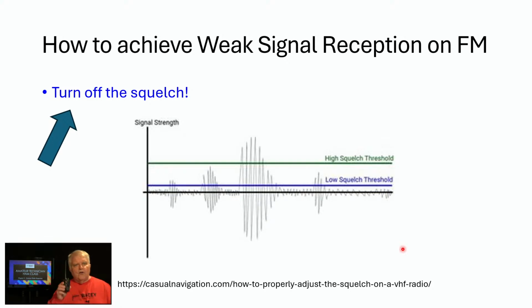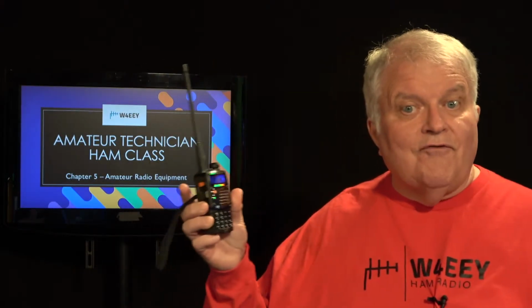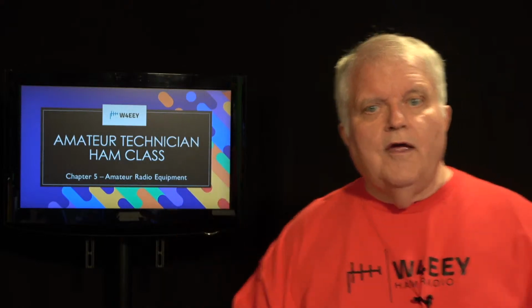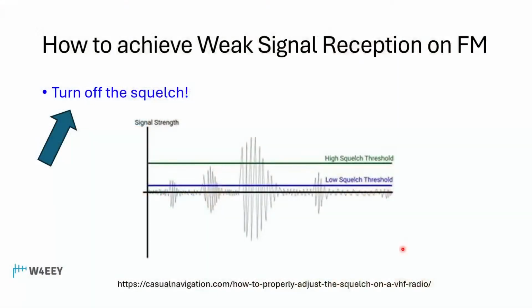Because with the squelch on, this radio is not going to hear weak signals. But with the squelch off, and if you listen very carefully, you might be able to hear a weak signal. So the point is that if you want to hear weak signals with a radio with squelch, you may need to turn that squelch off.